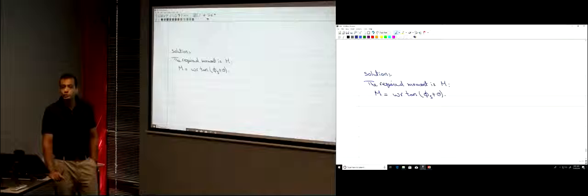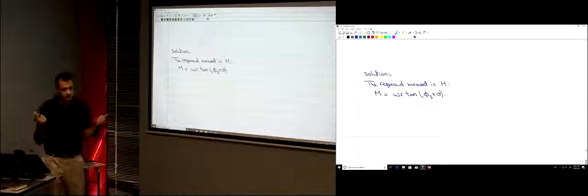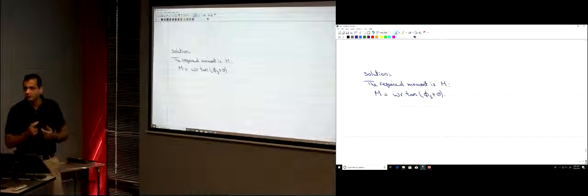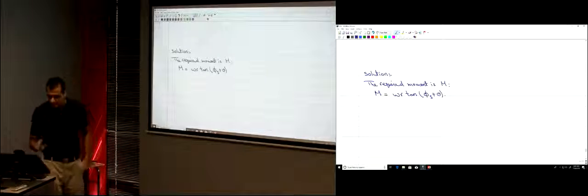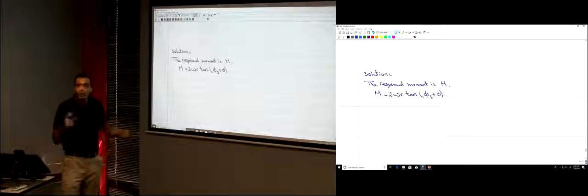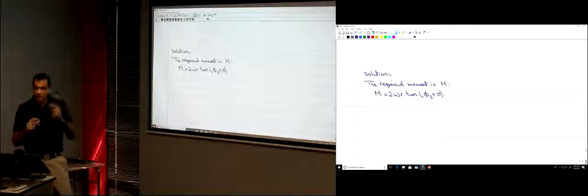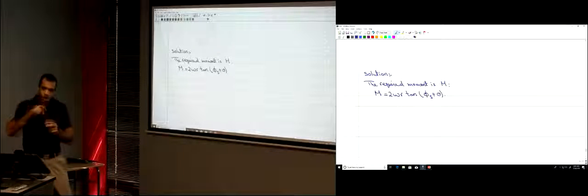Because you have two screws, the moment that you're going to apply is going to be divided by two screws. You're moving two parts here, so you actually require twice this moment to move both parts. The formula that we had was required to start the motion for just one screw.